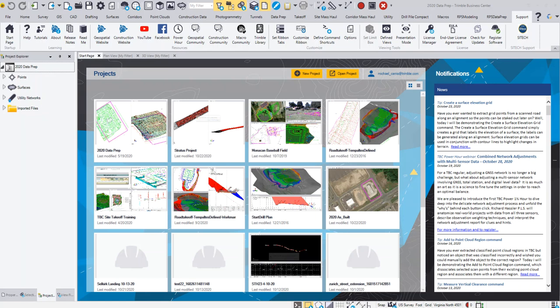So now I'm going to show you how to publish your data to the field. You're going to be able to use this process for legacy devices such as SCS900 devices or GCS900 devices, as well as the most recent SiteWorks and Earthworks systems. Also, you're going to use this process regardless of whether you're publishing it to the cloud, to WorksManager to send files remotely, or if you're going to stick it on a USB drive.